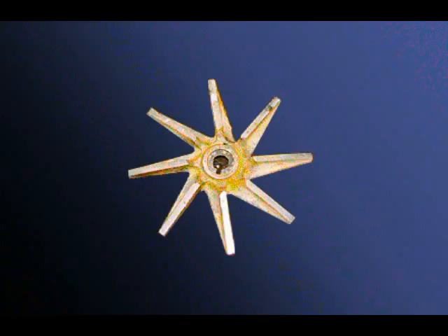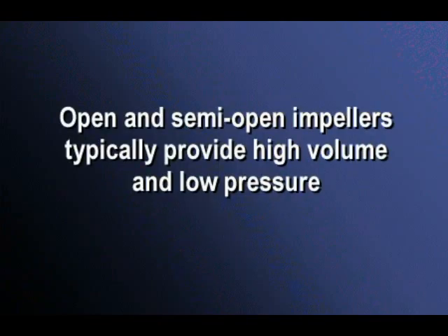Open and semi-open impellers are most often used to pump wastewater. Both impellers work well with liquids with a high solids content. These impellers are also generally a high-volume, low-pressure type of impeller, suitable for wastewater applications.